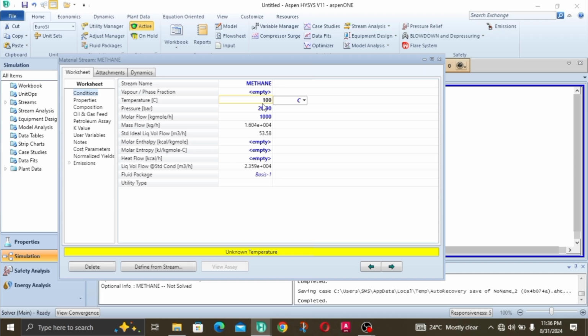Now, the reason why we are considering four properties is because we want to stick with these four properties because they are easy and self-explanatory. And when you are working on a process, an operation, you do normally have them on ground. That's the flow rate, pressure, temperature, and vapor fraction. But luckily enough, Aspen HYSYS does a very beautiful manipulation of finding the fourth one when we assign only three values. It doesn't allow us to assign four values because it causes a consistency error. It's normally three values. The moment we impute the third value, it automatically finds the value of the fourth one.